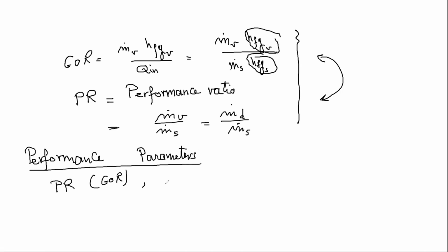We are looking for how much cooling water is coming to the system, because this means what should be the size of the pump that will bring the seawater from the sea, and that affects the capital cost of the plant. And area of the condenser and area of the evaporator.